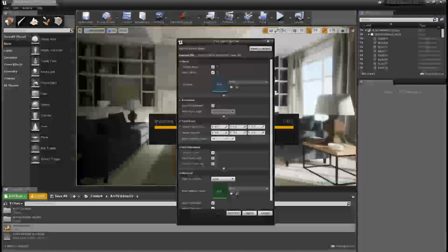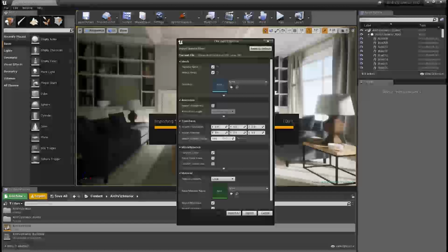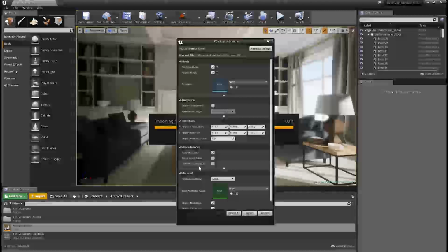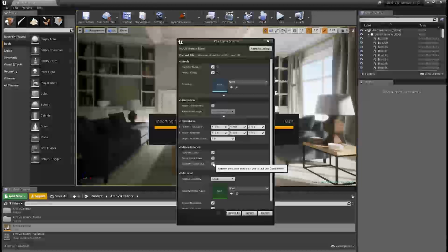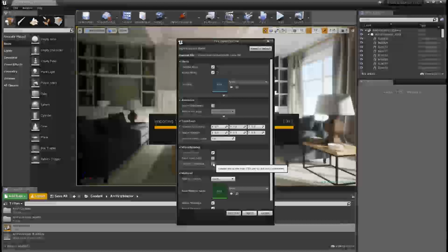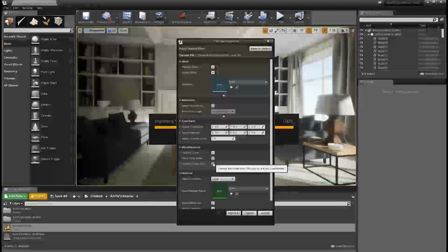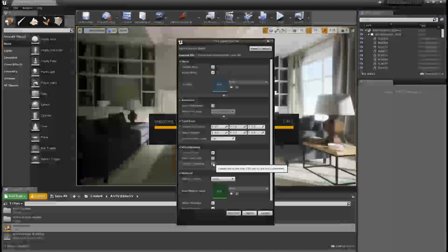We could do that. And under Miscellaneous, you can see here we have this Convert Scene Unit. We can convert the FBX units. Maybe we're working in Max generic units. We can convert those into the Unreal Engine 4 centimeter units. Now again, avoid doing this kind of one-off scaling. It's best to fix it in the source material, and then when you export it, it will come in the right size. In this case, our scene here, go ahead and cancel this because we've already got everything imported.